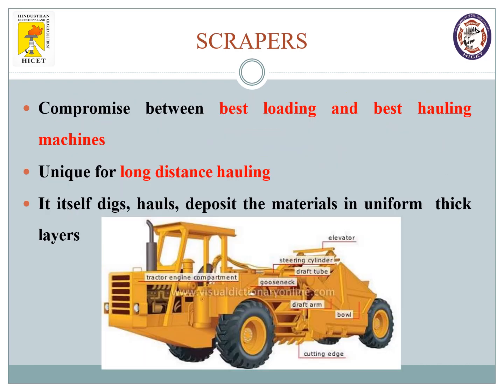The next equipment we are going to see in our earthwork is scrapers. This is a compromise between the best loading and the best hauling machines. When you are talking about best loading and best hauling machines, the combination is scrapers. This is unique for long distance hauling. If you need to take your materials over a very long distance, and if your loading is very high, then scrapers are the best equipment to use.